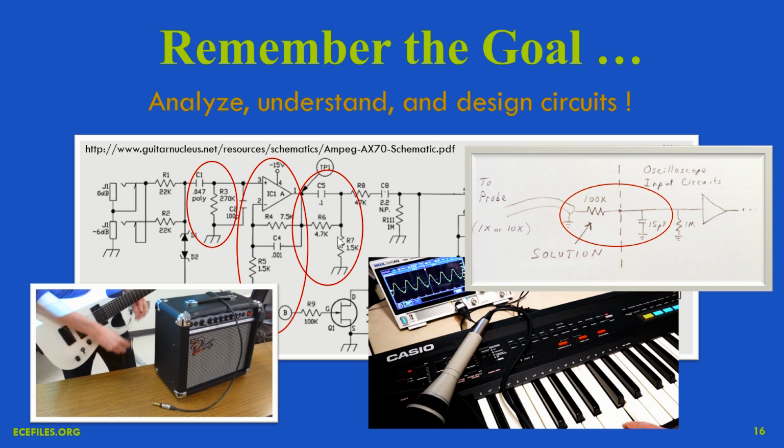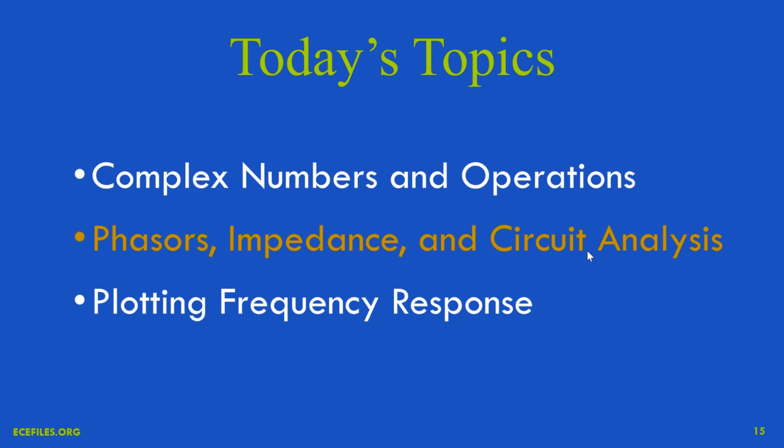And over here on the right, we've got this low-pass filter, and we've said previously that this capacitor shorts out high frequencies. Well, what does it mean to short them out? How much do they get decreased? They don't just suddenly go to zero. So that's our topic next, to talk about how you do circuit analysis so that we can eventually do our frequency response plots and answer those questions.